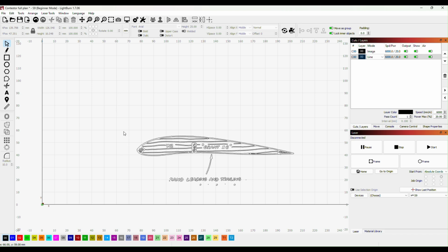Now I'll be using, as a former for the front leading edge, a 4.8mm square balsa, and the reason I'm going to use that is because these are supposed to be 3/16, but because of the extra weight with our radio, I want to increase the strength of the wing. So one tip that I had, a really good tip from one of the guys on one of the videos, was he uses a square.